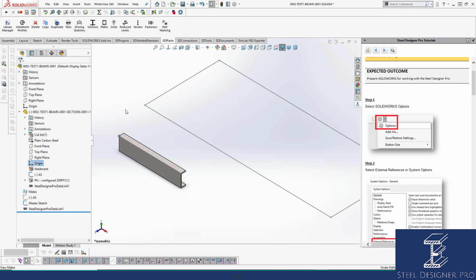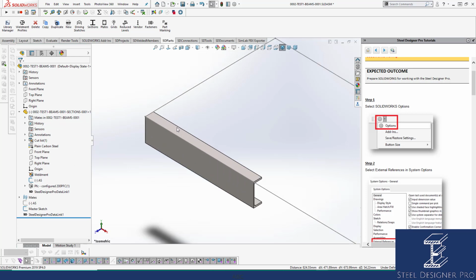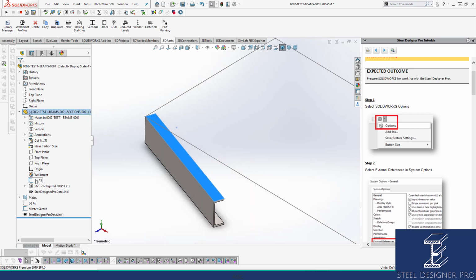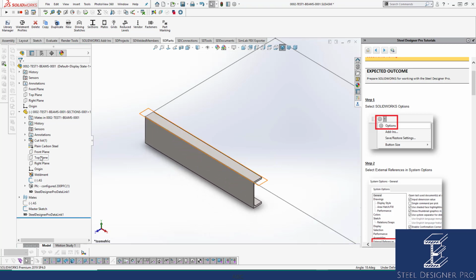So we select the origin, we select the sketch segment point, and we attach it by creating a mate. I'll do that again. So the next step is you've got the sketch segment on the end. You can just see me select it now, and then I select the sketch segment, and then I add a coincident mate. On the top plane and the top plane, I'm going to add an angle mate and make that 0 and hit my tick. So now this is fully defined. I can't move it. You can see down here on the right hand side, fully defined is gone. There's one more step. This has mated it in place.